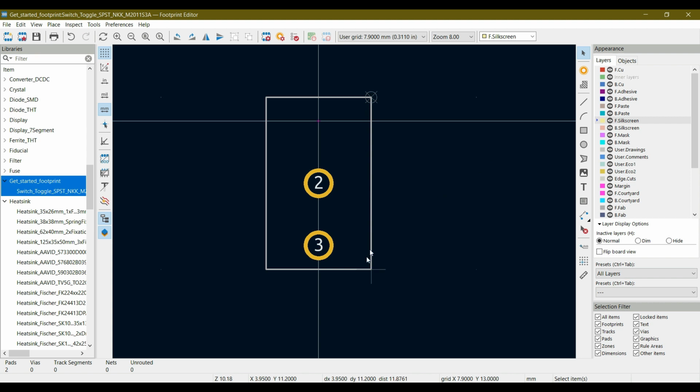The outline in the front fabrication layer is actually the part outline, so the silk screen lines are moved outwards from the fabrication drawing by 0.11 mm, which means that the silk screen line we draw will be only 0.11 mm out of the fabrication layer. So how is this done?